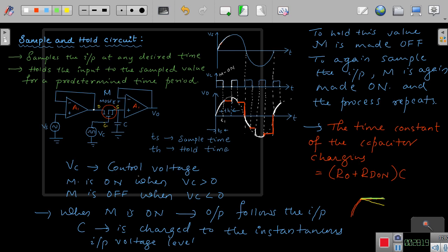But because of the bad dielectric nature of the capacitor used, or the very nature of the materials which are used in the capacitor, or there may be a small discharge in the forward path also. Though this resistance A1 has got a very high resistance, it is not infinite, right? So there will be a very small leakage current in the forward direction also, which can be neglected.